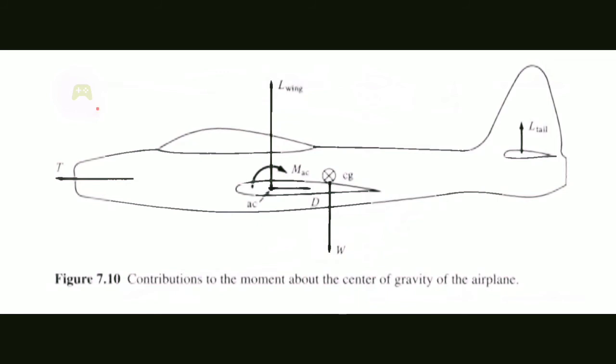Okay, so the lift and drag forces will create movement about the CG, and an airplane can be brought to an equilibrium position by controlling the amount of lift and drag forces, by deploying or deflecting the flaps according to the desire of the pilot. And the thrust force can also introduce movement about the CG if it's not in the line of CG.